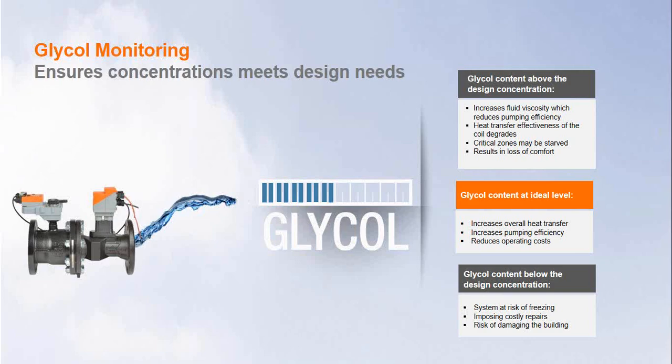Now, this is a very unique feature within this product, because to understand what that glycol concentration would be, it would require an additional device called the refractometer. So with that refractometer, you would have the cost of the refractometer, the cost to install the product, and also another additional control point to control that. Where now with the Energy Valve, you have that all integrated right into one device. So no additional components to install. The glycol percentage actually comes back as a BACnet point, so it can be understood by the system, all done with one single device and one single set point, optimizing your system and reducing your overall installation cost.